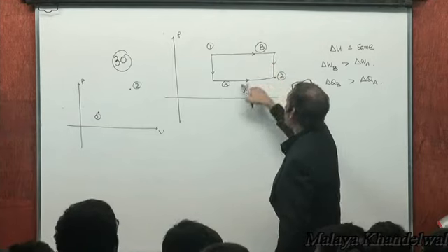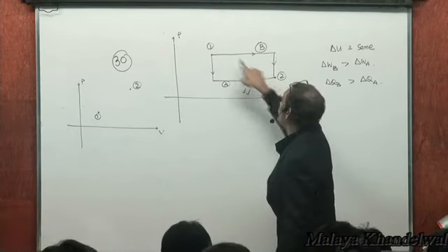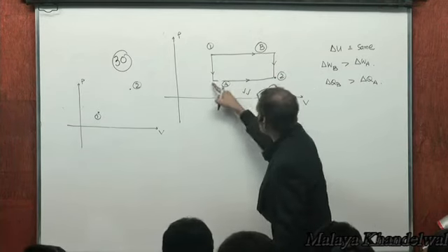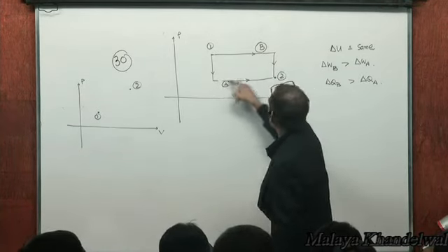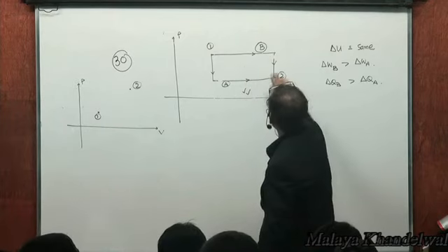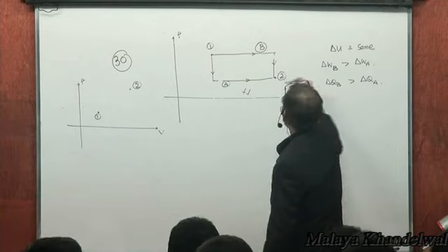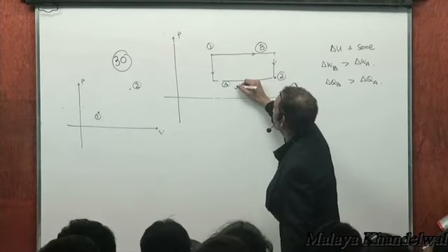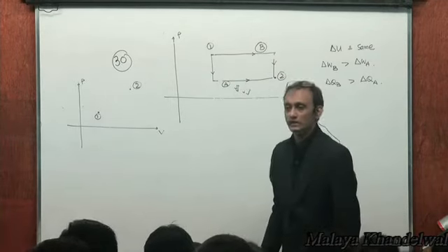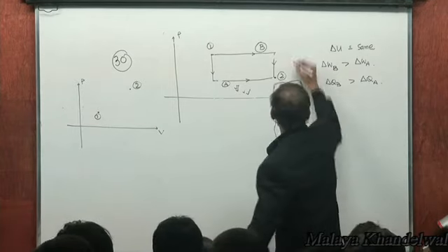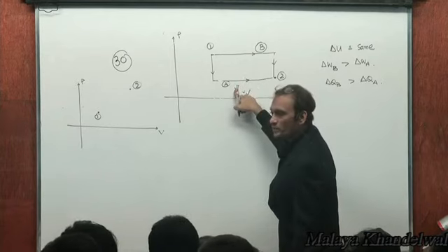In B and A, the change of internal energy is the same, but more work is done in B compared to A. The work done in A is simply this area. In B, the work done would be a bigger rectangle, right? Therefore, A should be preferred because it requires less heat. If this is the case, then A should be preferred.